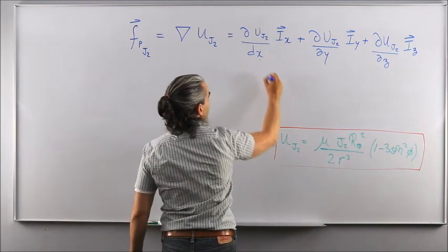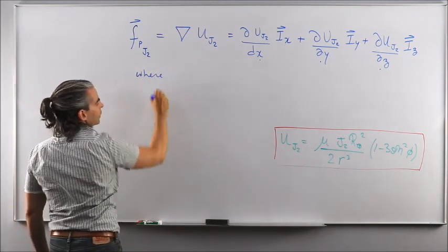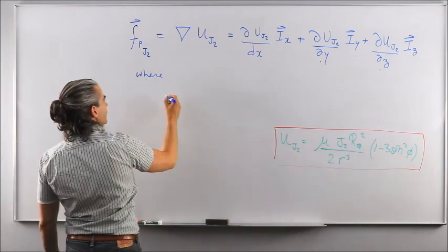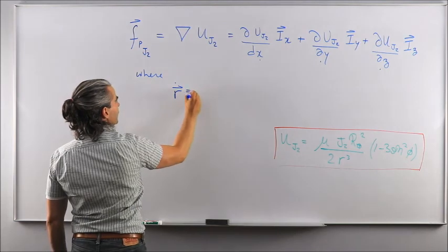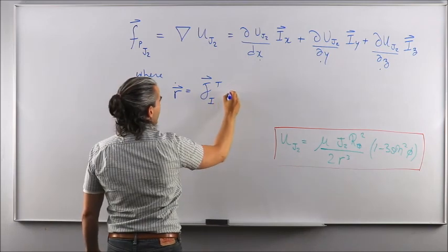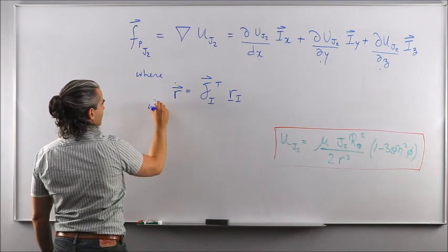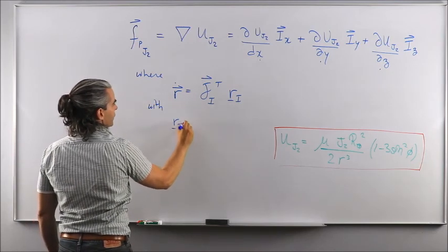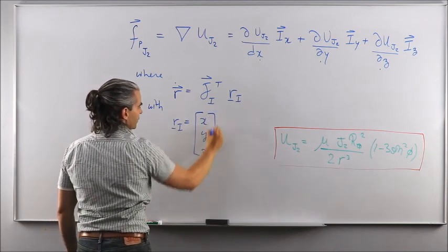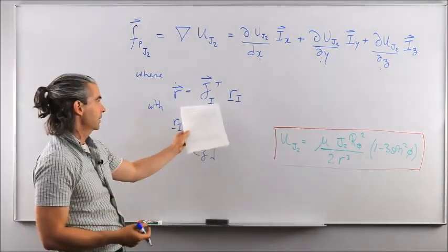Now those variables x, y, z actually correspond to the x, y, z components of the position vector r in ECI. So we're going to say r vector expressed in the ECI reference frame through its vectrix is going to be r I like this, with r I being equal to x, y, z scalars that denote the components of my position vector r seen from the inertial reference frame.